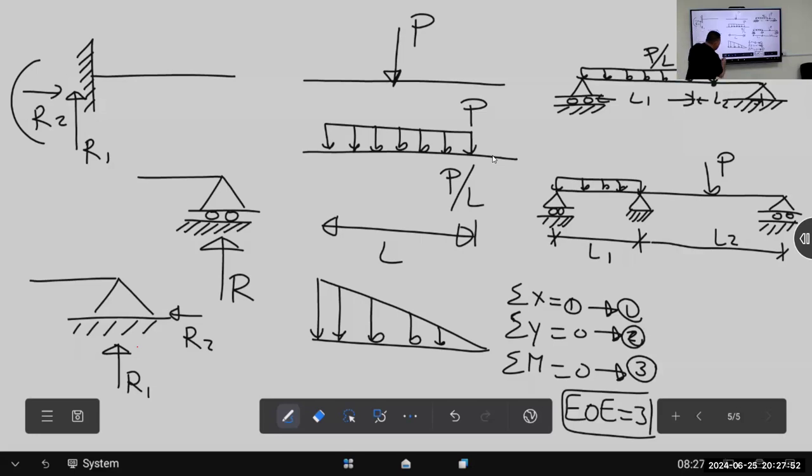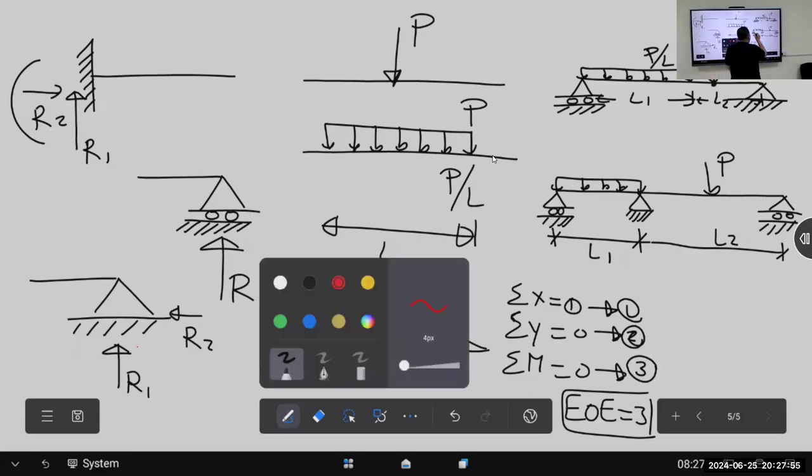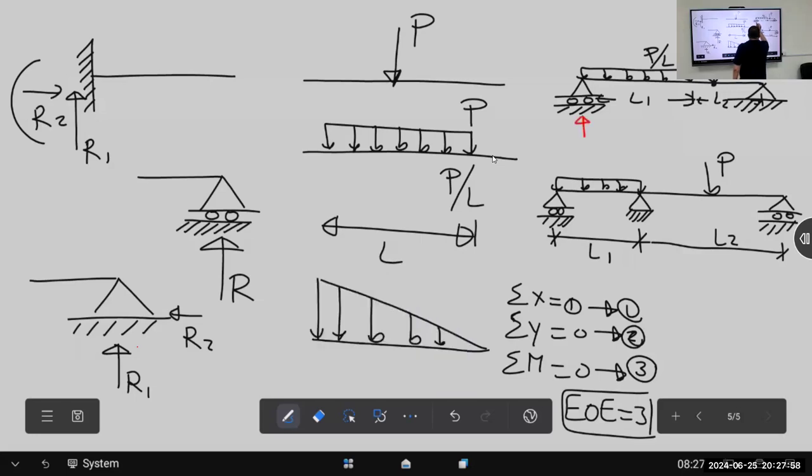Right. Let us go for the simply supported beam. How many reactions? At A, one reaction only, Y_A. I will not put 2. Why should I put 2? This is a roller support. How many reactions? 1. At B, Y_B and X_B. You now have how many reactions? 3. These are now unknowns. Do I know them?